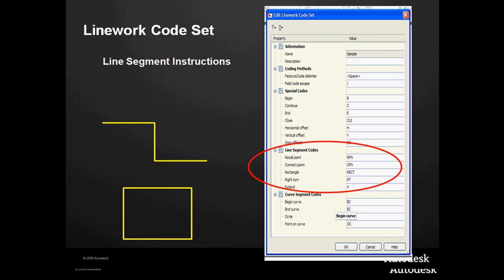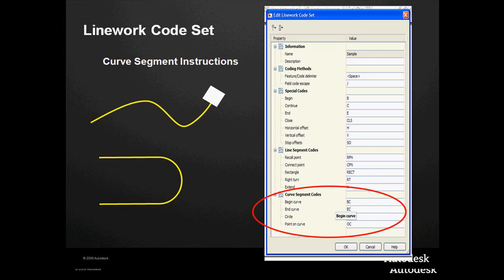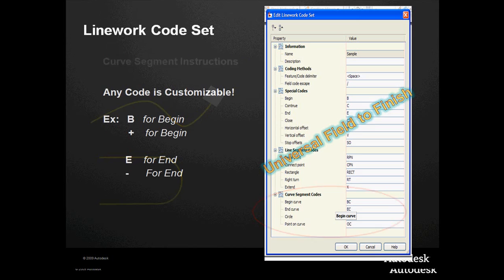So if I'm going to take a shot at the end of a curve or something that's here, and there's a tree that's blocking my line of sight, I can actually go past that if I'm connecting a line. I can take a shot here and then put in a negative value to automatically shorten up to where the shot actually is, or I can give it a positive value to continue to extend the line until where the end actually would be. All right, so lots of stuff that it would be very difficult for us to accomplish before. Finally, we have curve segments, multi-point curves, one-point curves. We'll take a look at those as well.